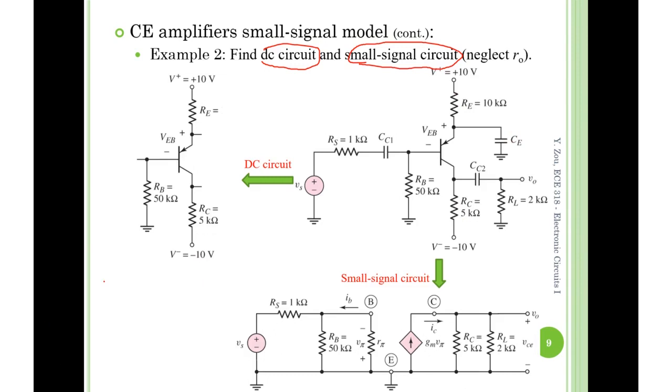Yeah, this is another PNP. You need to be careful which resistor is which. The emitter is on the top, so that's why the connected resistor is called RE. Yeah, I need to start writing names and not numbers because I'm getting the numbers backwards sometimes. Or you can just write numbers, neglecting the names.